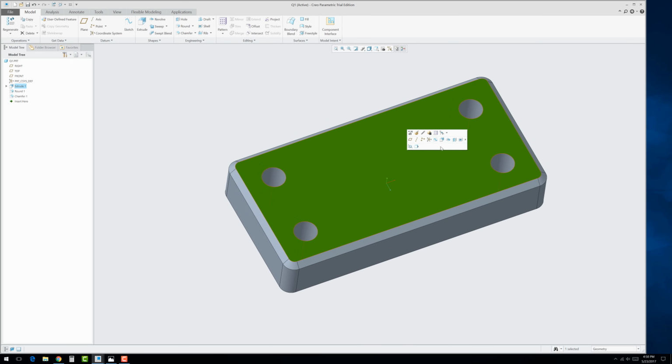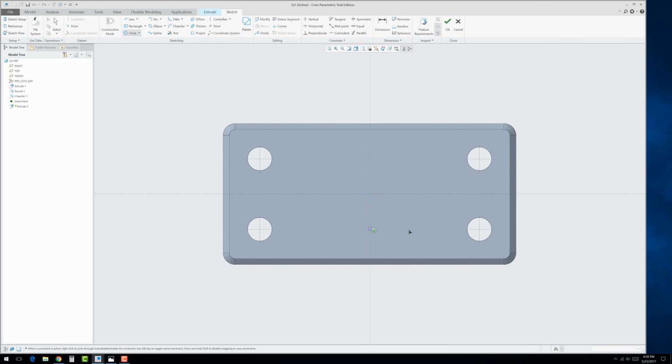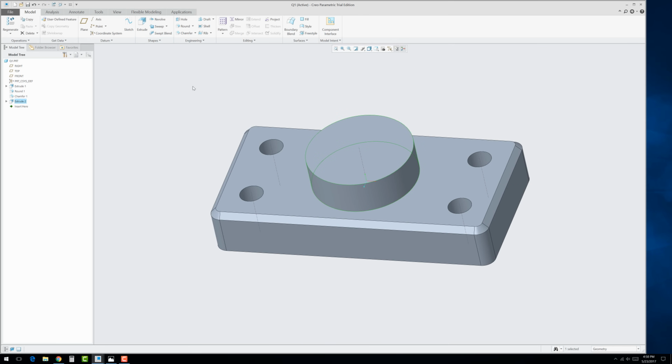Click. And then look at, we have extrude. Let's go to extrude there. Okay, draw a circle right at the center. That was the benefit to drawing it centered. And I'm afraid I don't remember what that is. That's 2.25. And notice there's no hole yet. Just hit OK. And this reaches the height of 0.75. Hit the green check mark.